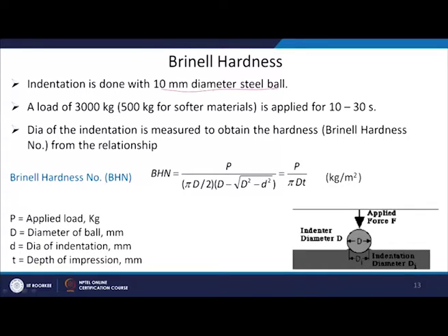So you have to have an indenter to measure the properties. The first idea which was proposed to find out the hardness was a 10 millimeter diameter steel ball, okay, you press it into the material, okay. So the impression which it creates on the material will give you the indication of the hardness. So if it is a hard material and I press this steel ball, it will give you a smaller impression. If it is a soft material and I press the steel ball with the same load, okay, it will give you a bigger impression. So you can at least find out which is the soft material, which is the hard material.